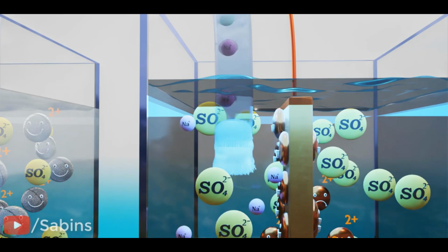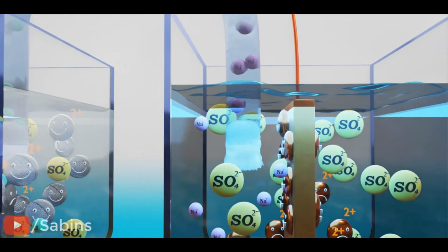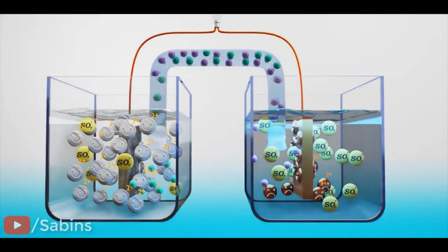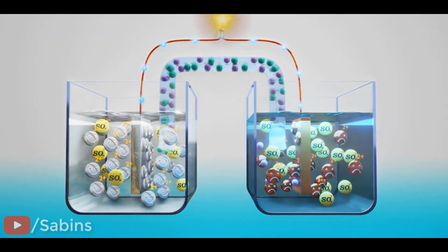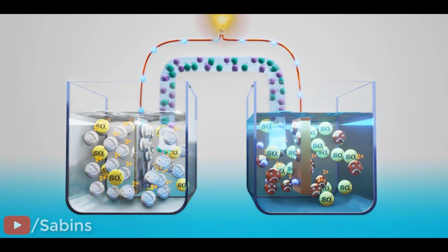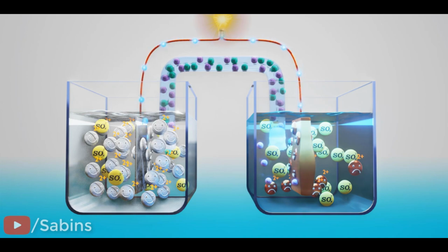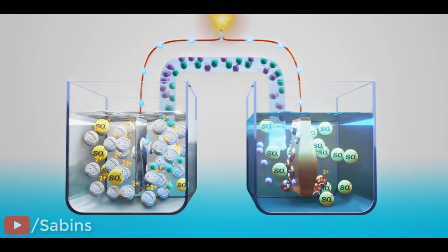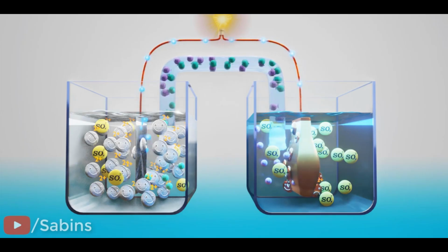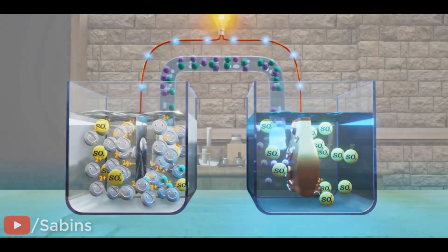The explanation is purely thermodynamic, since the reduction potential of zinc (-0.76 volts) is much more negative than that of iron (-0.44 volts). Zinc acts as a consumable anode. It preferentially loses electrons, forcing iron to remain in its oxidation state zero. In other words, it cathodically polarizes the iron and prevents its corrosion.